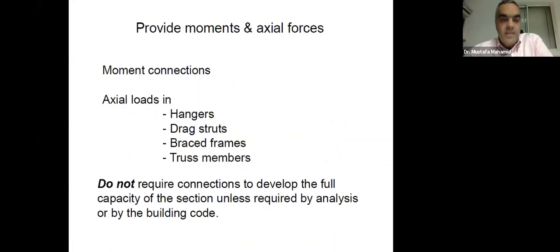Provide moments and axial loads. Also moments, that's another thing that I have seen and always requested. Whenever I design connections for fabricators, I ask them to go back to the structural engineers and provide moments so we can design for actual loads.